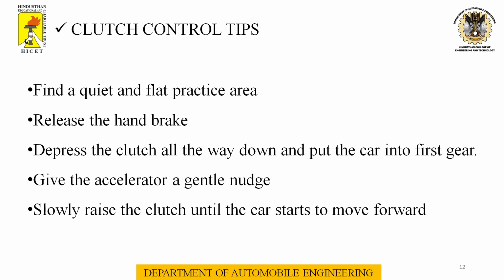Important tips for controlling the clutch. Find a quiet and flat practice area. Release the handbrake when you start riding. Depress the clutch all the way down and put the car into first gear. Give the accelerator gentle pressure. Slowly raise the clutch until the car starts to move forward.